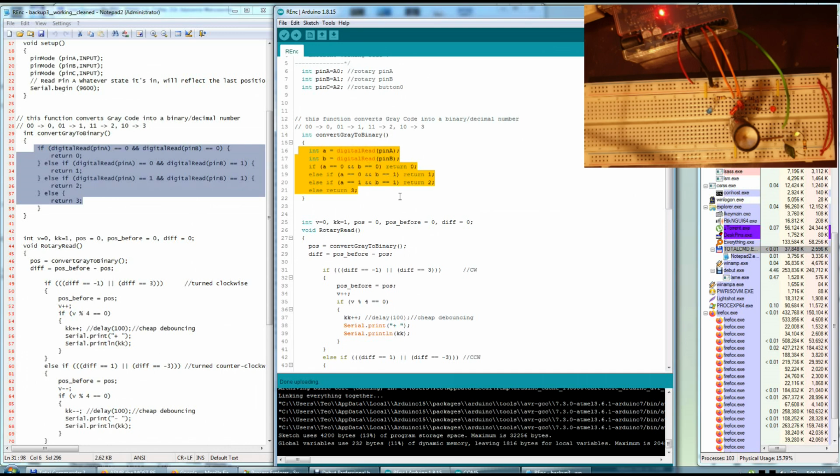What it is doing on this other side, I'm reading only once these two pins, but inserting them into two variables, these A and B variables, and then I'm playing only with the variables, but I'm not reading the actual pin. So even if the knob is bouncing or actually turning in the middle of the checking, what it is doing inside here, because this is all it's doing, is checking. If that is 0, if that is 1, it is a sequential checking of what it is doing here. Like in this comment, it is very clear.